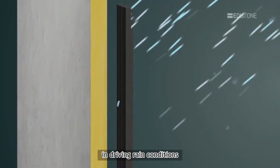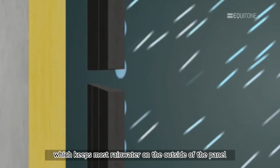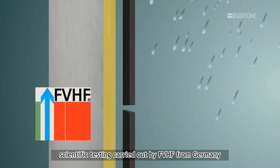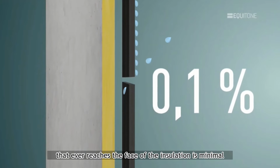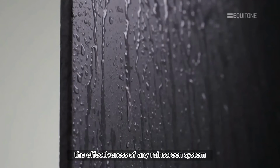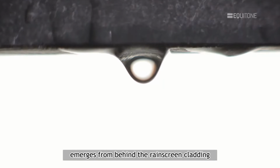In driving rain conditions, the moisture forms a membrane across the joints, which keeps most rainwater on the outside of the panel. Scientific testing carried out by FVHF from Germany has shown that the amount of driving rain that ever reaches the face of the insulation is minimal. The effectiveness of any rain screen system can be checked by standing at the base of a large installation in the driving rain and observing how little water emerges from behind the rain screen cladding.